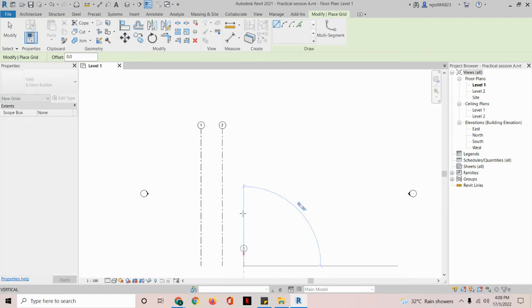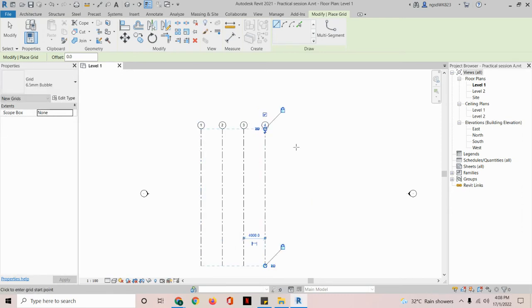So for example, I click another one, it will be a 3, and then I click another one, it will be a 4. You guys don't have to follow 100%. Just put it as wide as you like, maybe about 3 to 4 meter is good enough. So let's create about 6. Give you guys a while to create about 6, let's say until 4:09. I'll give you 1 minute to do it. You should end up with something like this. Just click 1 and 2, and then you will have one grid line. Try it out.